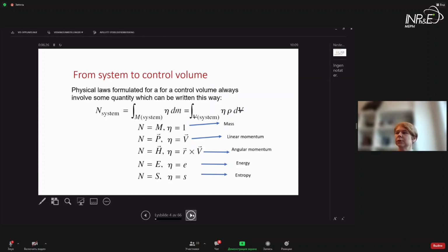But fluid mechanics is fundamentally different in this way: we don't have this lump of mass. What we have instead is what I call an observation window through which this mass of fluid, whether a gas or a liquid or a combination of these, flows. We call this window a control volume. So when we introduce quantities like mass, linear momentum, angular momentum, all these important physical quantities, they are what we observe flowing through this observation window. This concept drives all these formulas and is why it looks so special.